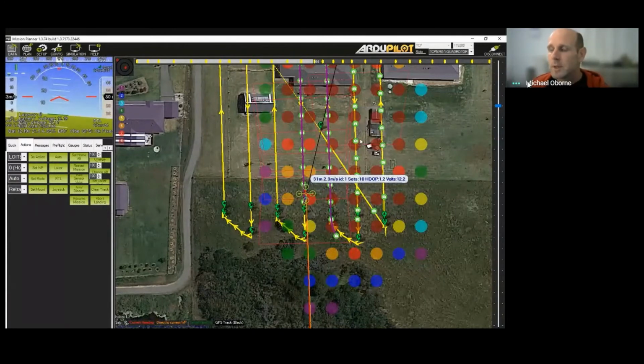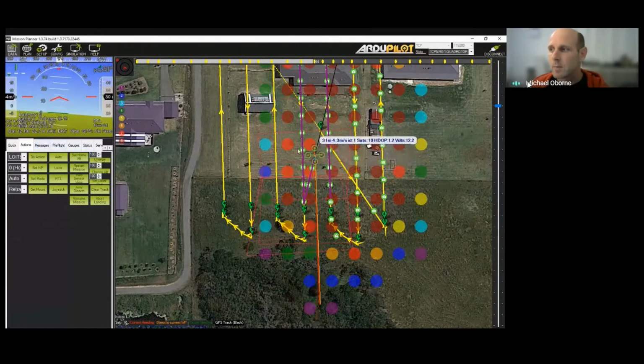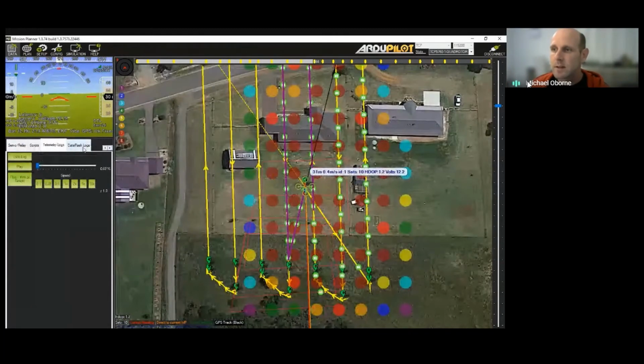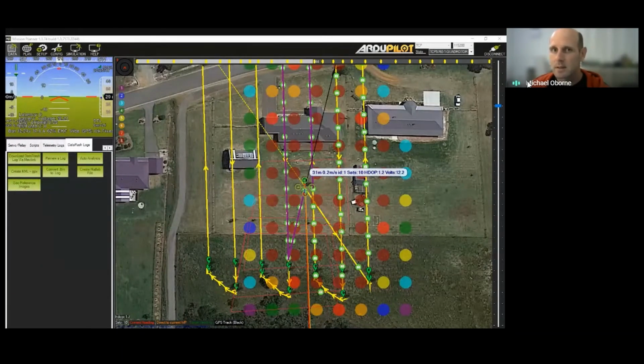So assuming you just got all these photos, so I've disconnected, I'm going to basically download the data flash log. So you download the data flash log. Oh, I can't do it now because I'm in the air. So what I'll do is, I actually have a demo here where I can show how you'd use the Geo Reference function in Mission Planner.